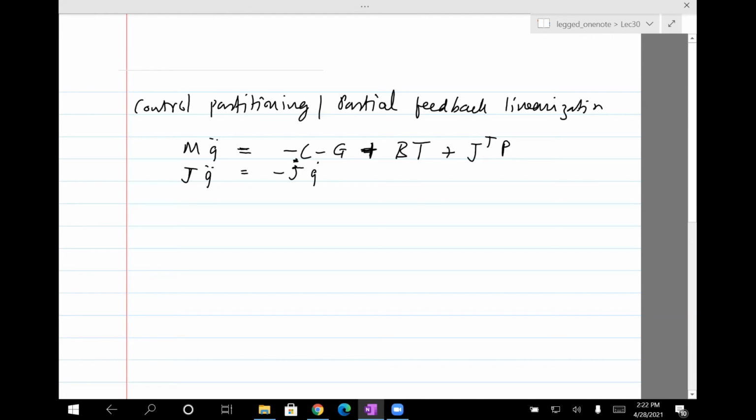Maybe we've done this in the closed chain. So in the closed chain, I did have a force in the equations, and I had to get rid of that force because that force is really not contributing. Well, it's basically a constraint force which in a different coordinate system will go away. So in this case, the force is there because I chose the position to describe the floating base at the hip. If I had chosen that point to be the foot location, then that force would have gone away, right? Because that point is basically stationary.